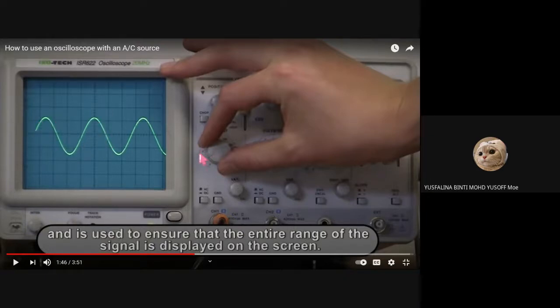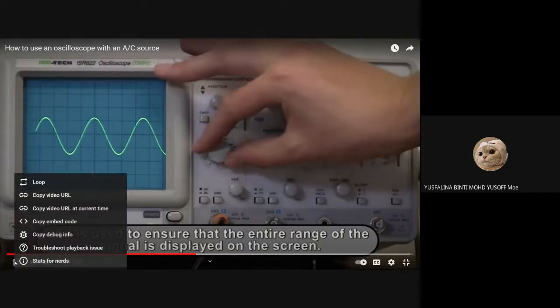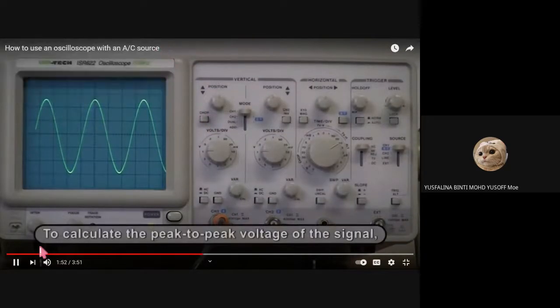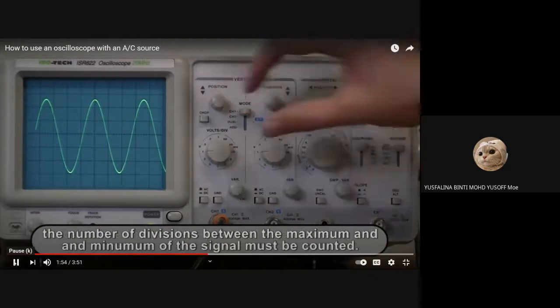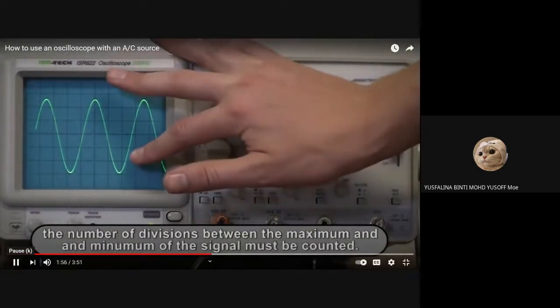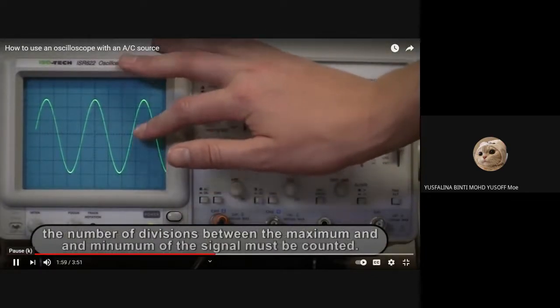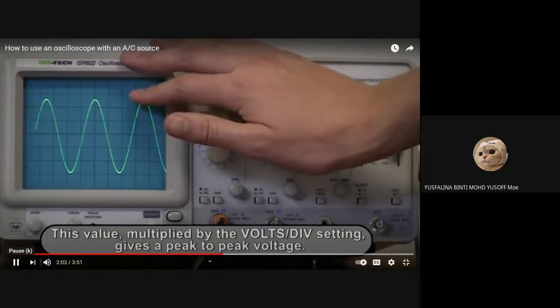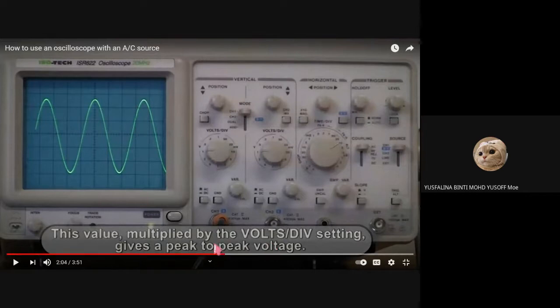So you can change here. It depends on which one you want to use, and what is easy for you to read the voltage. To calculate the peak-to-peak voltage of the signal, the number of divisions between the maximum and minimum of the signal must be counted. This value, multiplied by the volts per division setting, gives the peak-to-peak voltage. Okay, so for this I will show you.